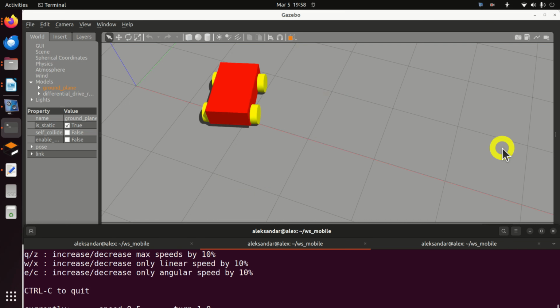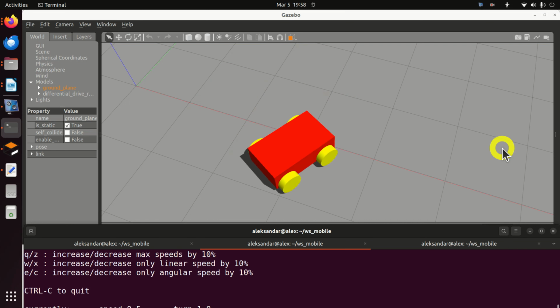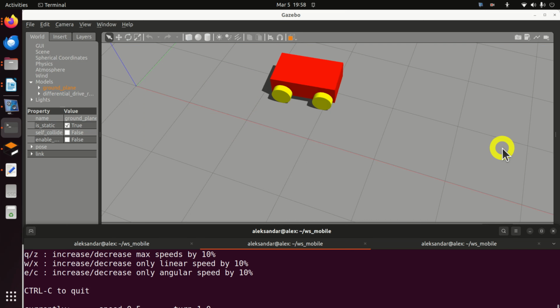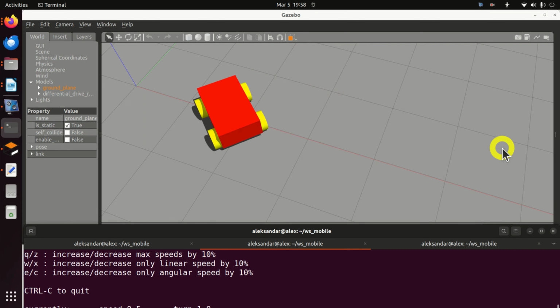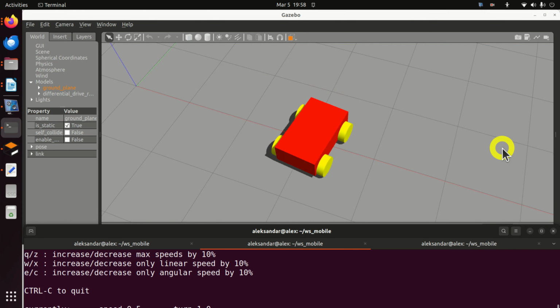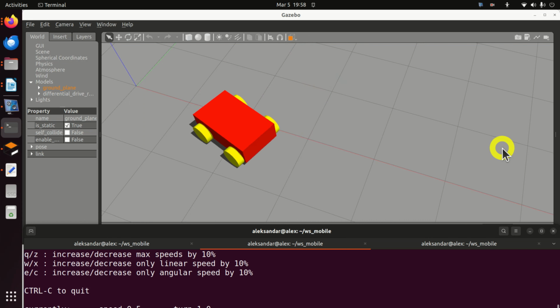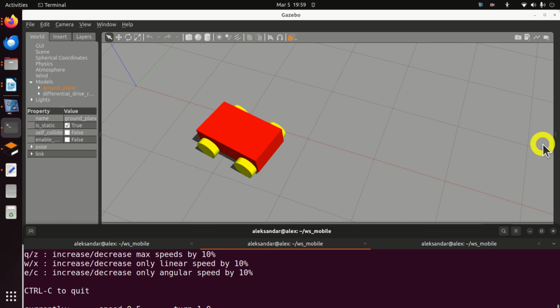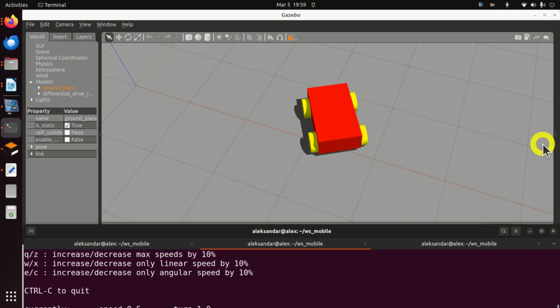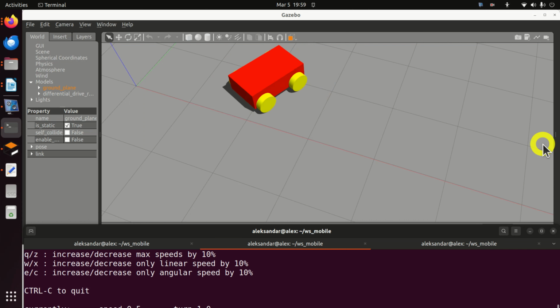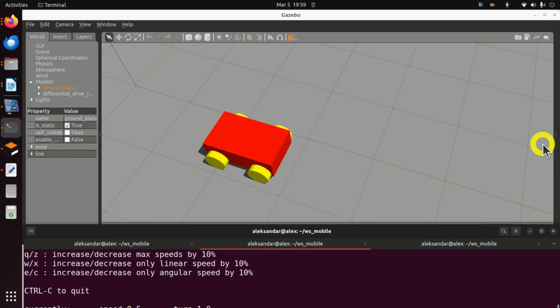Namely, to model the robot in ROS2, we had to write a completely new launch file and to significantly modify the Xacro model files, such that the model could be properly displayed and simulated in Gazebo. Furthermore, the process of building the workspace and packages in ROS2 is completely different from ROS1.